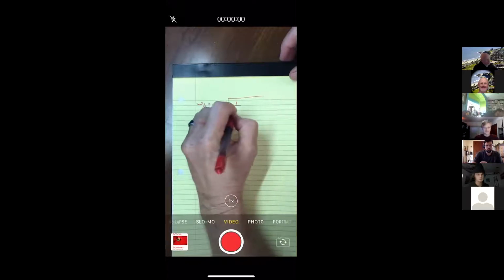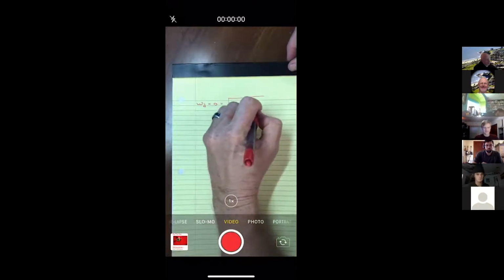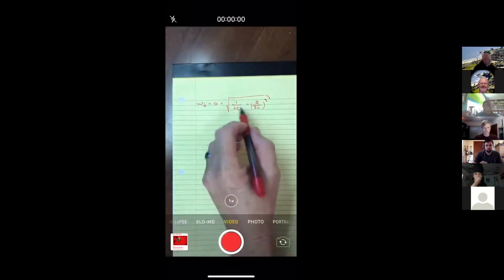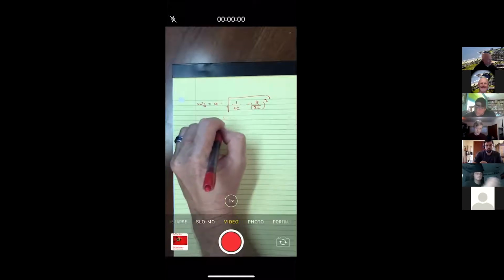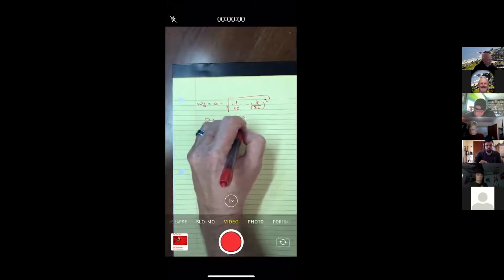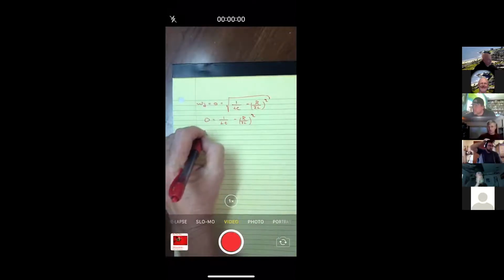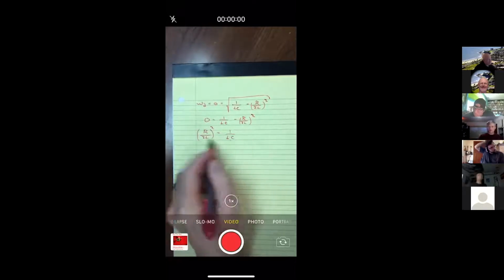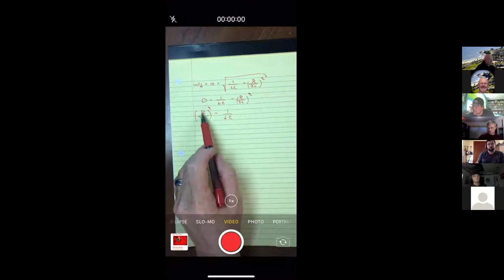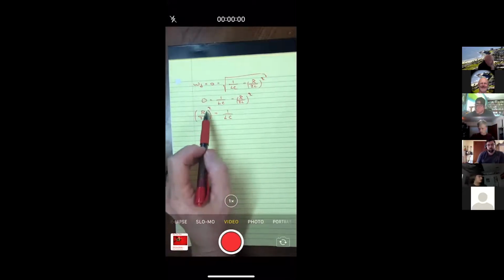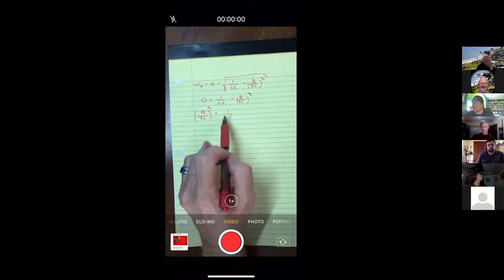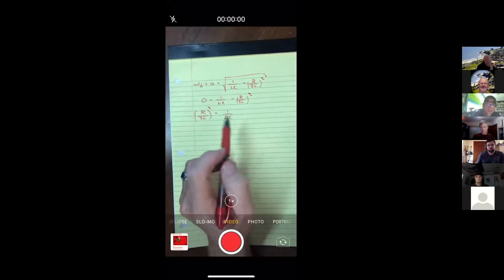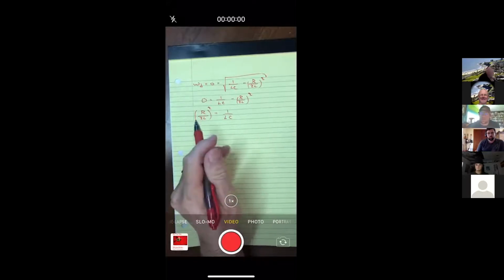And so if you take the square root of LC minus R over LC and you square it, well, I'll just square it to get rid of the square roots. I get 1 over LC minus R over 2L squared. Move this to the other side. And when this condition matches, when you have so much resistance that the left-hand side is equal to the right-hand side, if you have that much resistance, you don't get any oscillations.